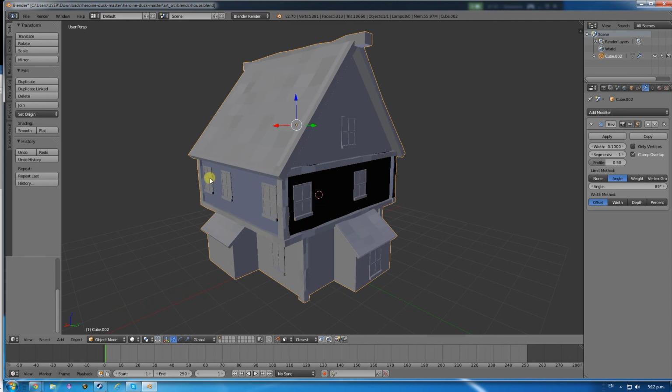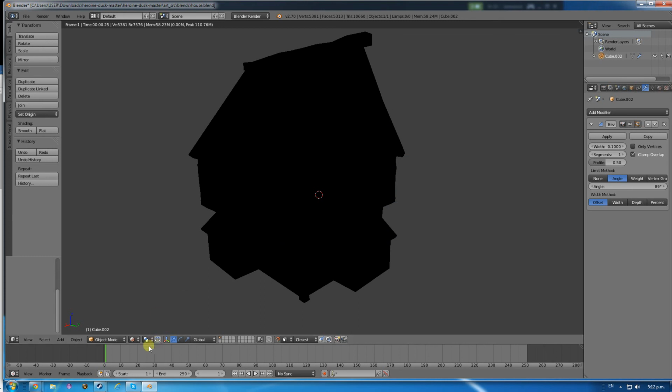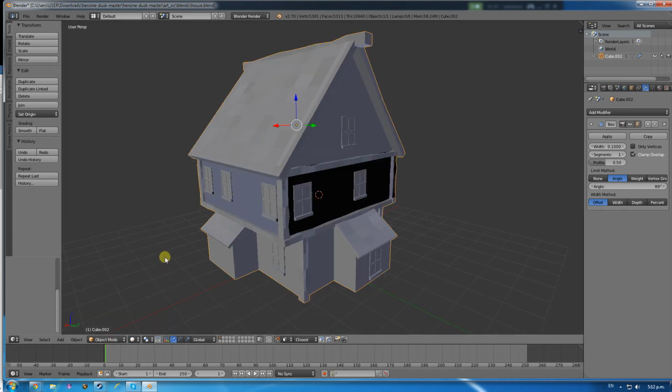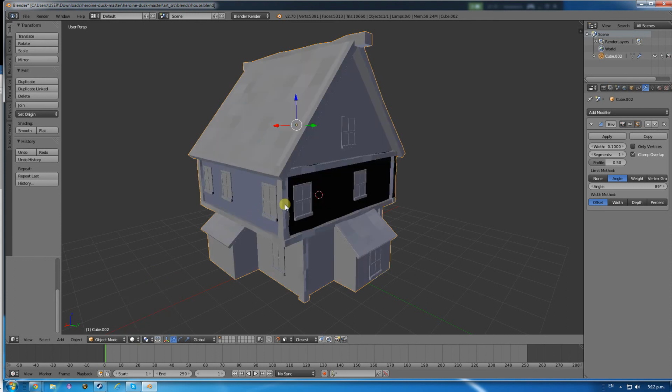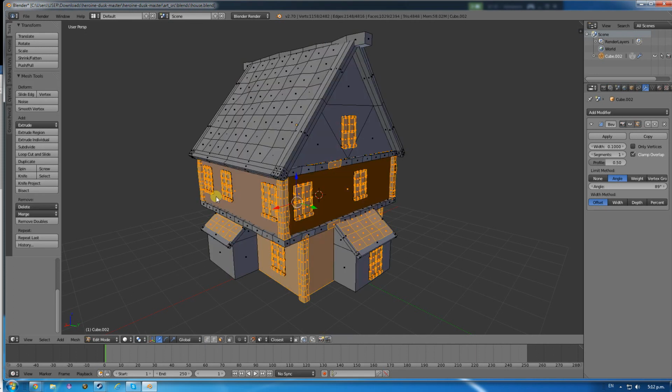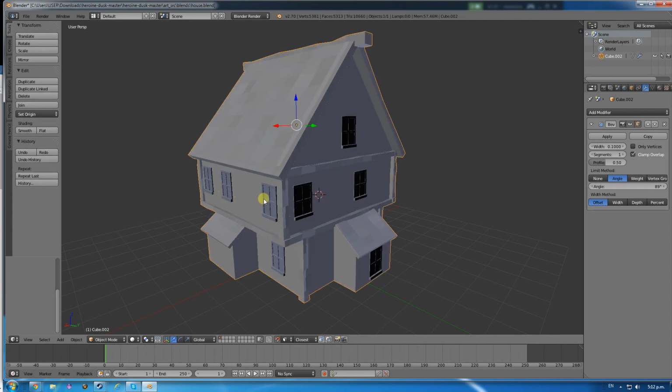But all of this part here has gone inside out, which means when you render it, where there's no light source, part of it will be invisible, which I don't want. If I look at texture, no, it's not going to work. So these darker parts will be invisible. Anyway, to fix that, I just go into here, select everything and push Control N, and it should sort it.